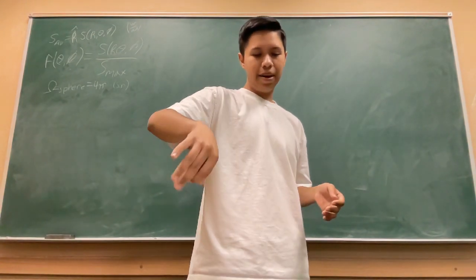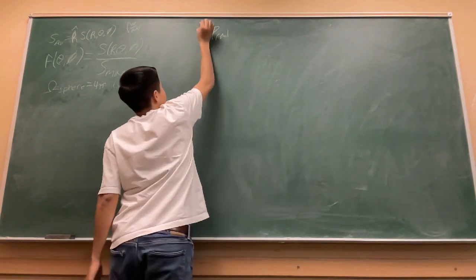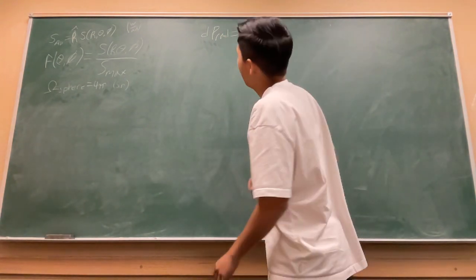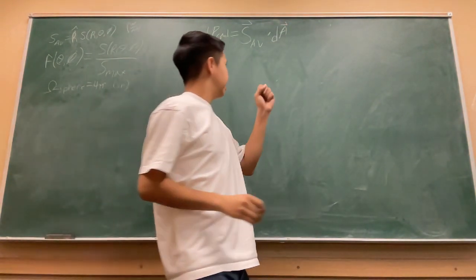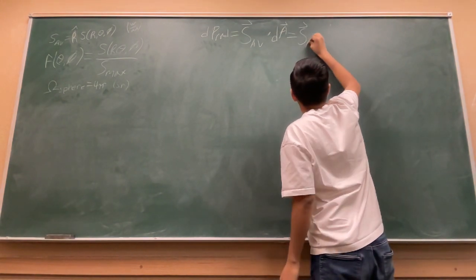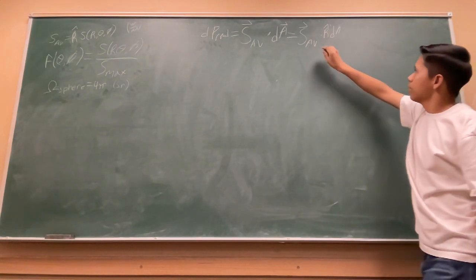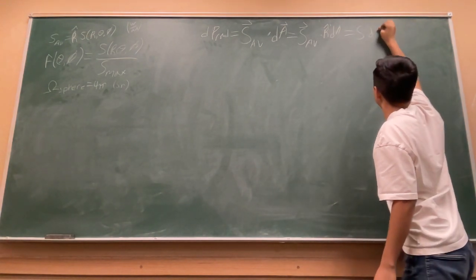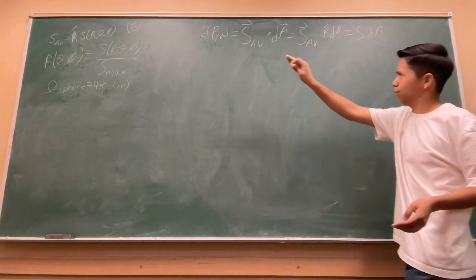So in order to find that plot, we're first going to start by finding the power radiated by the antenna, but in order to find that, we're going to do a differential power radiated, so we can derive that. This differential power radiated is going to be equal to the average power density dotted with a differential area vector. So just a really tiny area. When we do the dot product of that, we can actually simplify it by taking out the r hat. So we're going to be left with the average power density times r hat, and then a differential area. The dot product of these two, the directions will cancel out. This has a magnitude of 1, so we're going to be left with just the power density times a differential area. The units of that are watts per meter squared, and an area is meters squared, so obviously we're going to be finding a differential power with this.